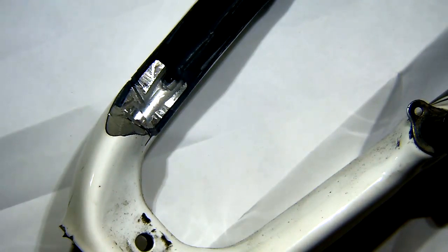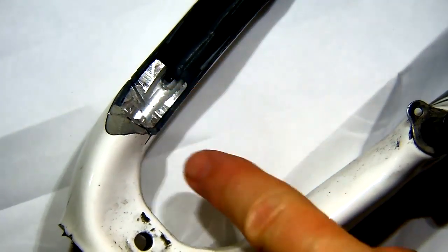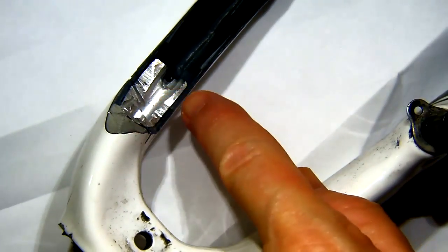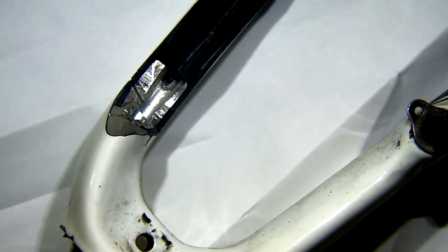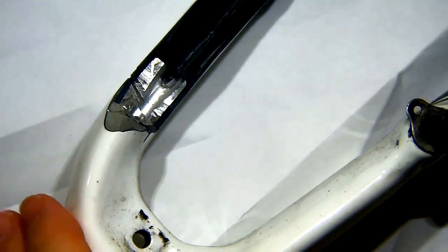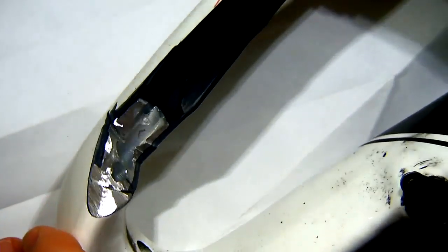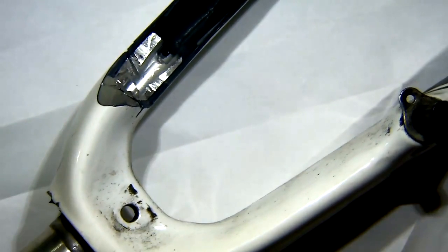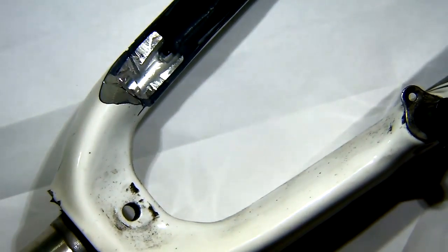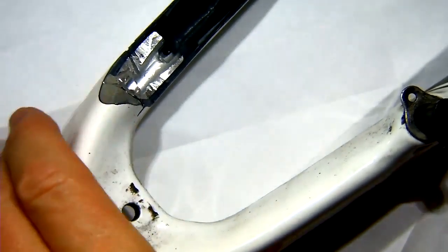Investment casting is what we're talking about. So at either end there's a casting. We have to have tolerancing to be able to allow for the carbon fibre strut to slot in. There's got to be a big enough gap to allow a bit of glue. That's how this thing's been attached. And then we ask, how precise does it need to be for a push bike? And the answer, of course, is we're looking at price point. We're looking at cost. It's not aerospace. So you could imagine it's not going to be as fancy. And the same thing is happening down at this end.